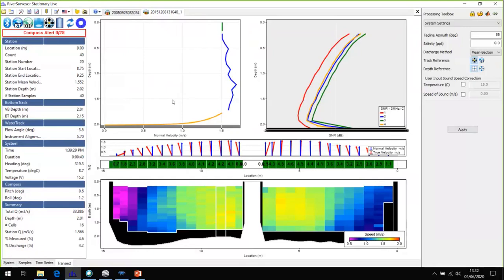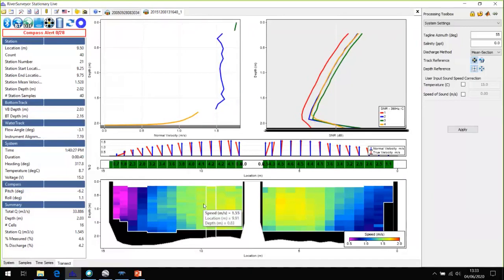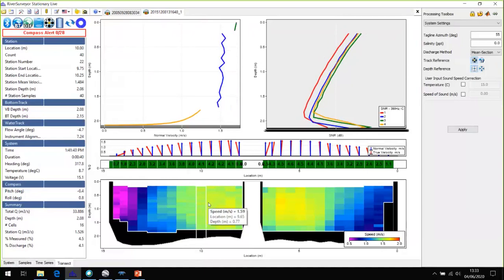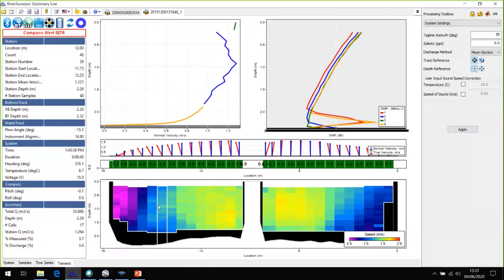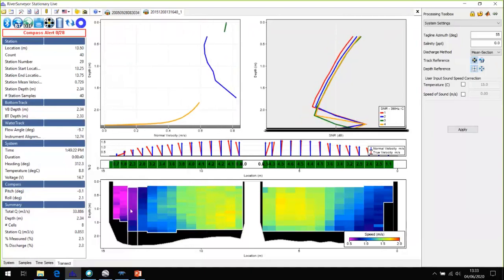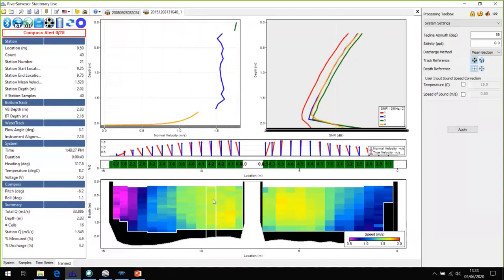That's a consequence of your sampling. How long are you sampling? 50 seconds? This one's 40 on that one. Yep, yeah, we do 50. I wasn't going to go too much into extrapolation because you did a very good webinar on it, but an advantage is that you can get a really good picture of a nice big window and set extrapolations like we've been talking about, the problems with moving boat extrapolations. We can put the right extrapolation for each part of the river very easily. So we're not applying constant ones across if they shouldn't be applied.